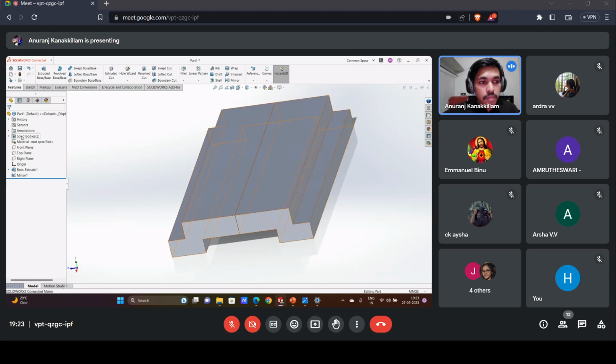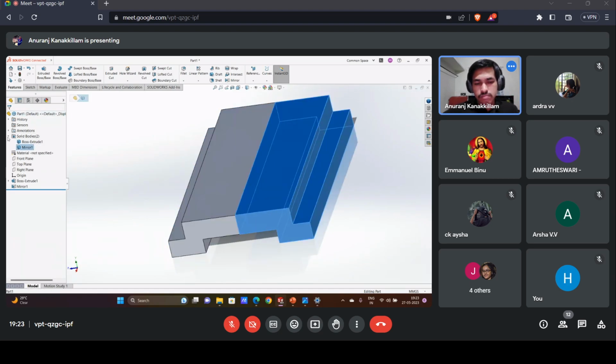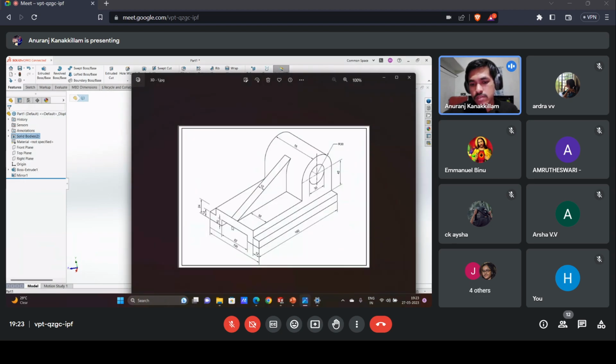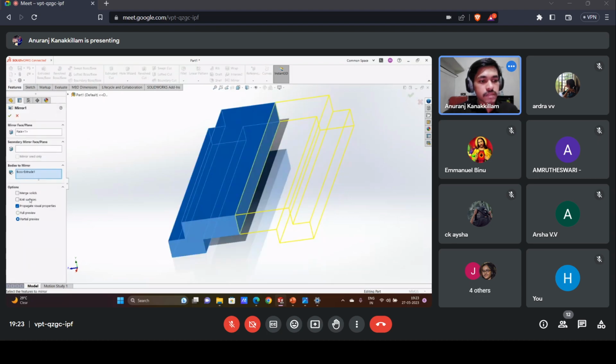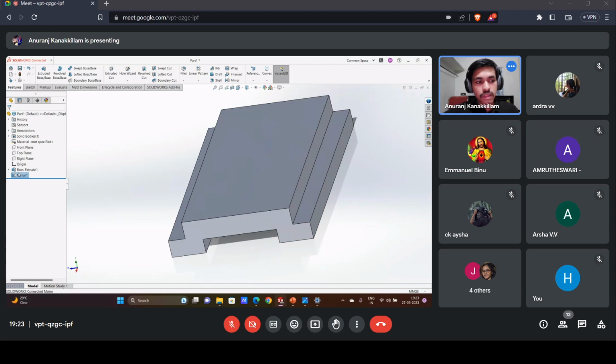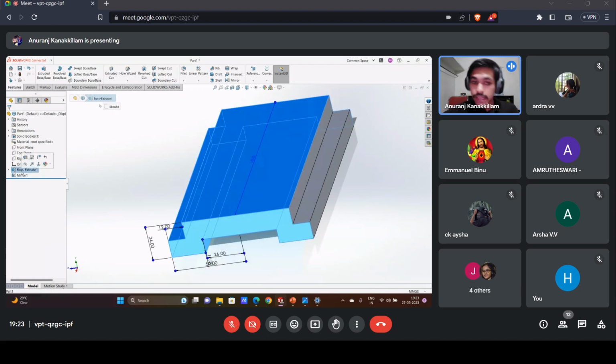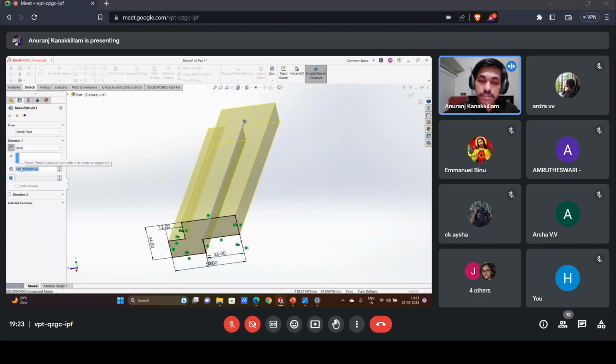So here we could see that solid body number two. We have two bodies, one body, two body. Since here we couldn't see any separation, we'll go with single body. So again, edit feature, merge solid, done. You can edit the first extrusion. You can go change this 160 if you made any mistake, or if any last minute updates come, you can come here and edit.